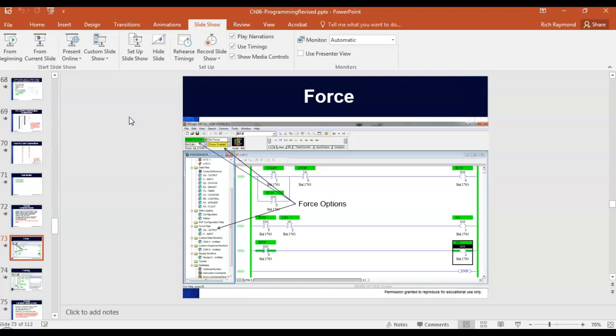So be really careful. I think I showed y'all, some of y'all have been back there at the line. Just about all your power relays, you have the ability to manually override them or force them. I mean, did I tell you about the guy up in number 8 Glassburn, where they forced a relay and cut him in two? He simply pushed the wrong relay. And they didn't lock it out.